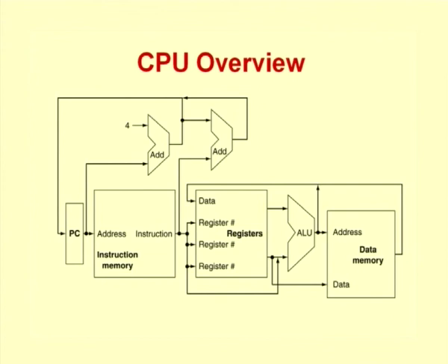And we will also use the same ALU if we want to calculate the memory address for a load or store operation. Let us look at it step by step. Suppose it was only an ALU instruction. What do we do then? The output of this ALU has to be stored back in a register. So, we need a path from the output of the ALU to the register file, so that you store the value back.